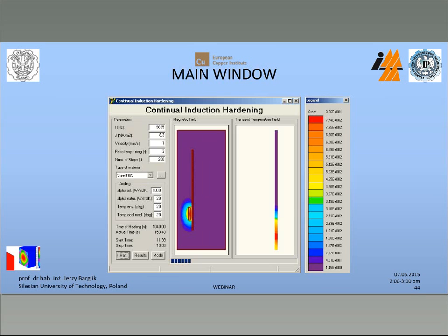And quite good results were achieved, quite good accordance between simulation and measurement done on the experimental stand. Of course, there is one important problem here. We have a 2 meters long tube, and you should move the tube from the lower position to higher position. You should have 2 meters long bus bars. So it is a problem of optimization, how it would be arranged, because losses in these bus bars should also be taken into consideration.